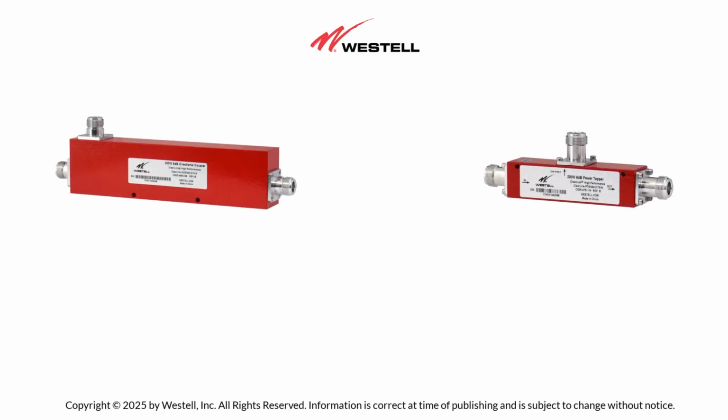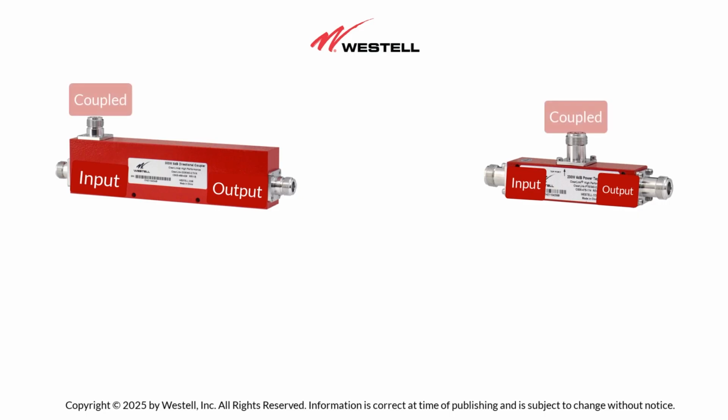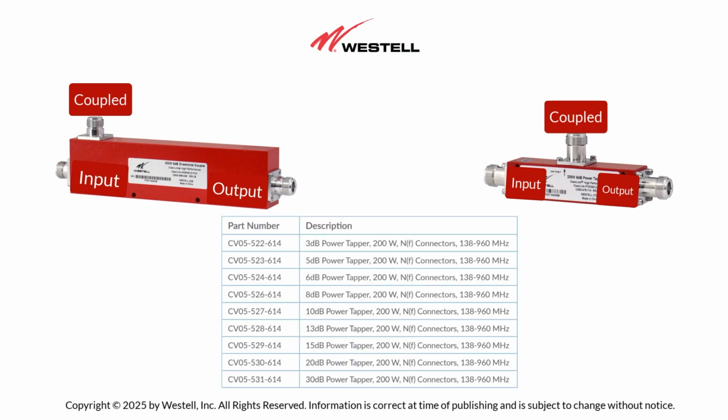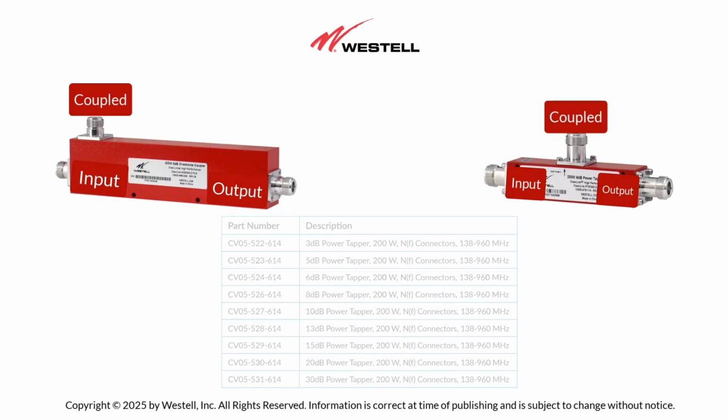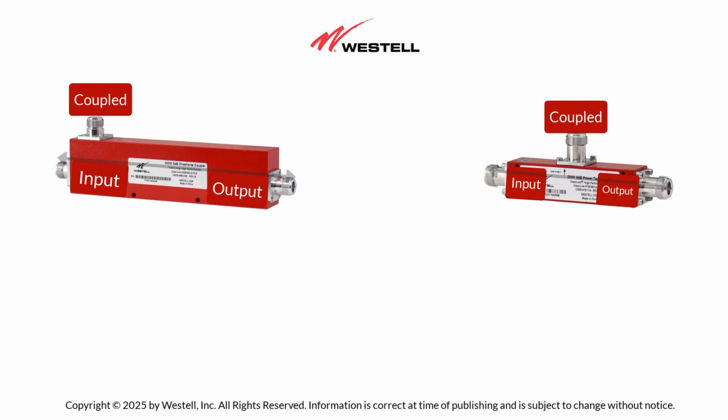Let's examine the similarities and differences between directional couplers and tappers. Both devices feature 3 ports. The 2 outer ports are typically referred to as the input and output ports, although they may not always be labeled as such. The middle port is known as the coupled port, which is associated with attenuation. The level of attenuation varies based on the specific model, with examples including 6, 8, 10, 13, 15, and 20 dB, among other values. When a signal travels between the input and output ports, different losses can be expected.